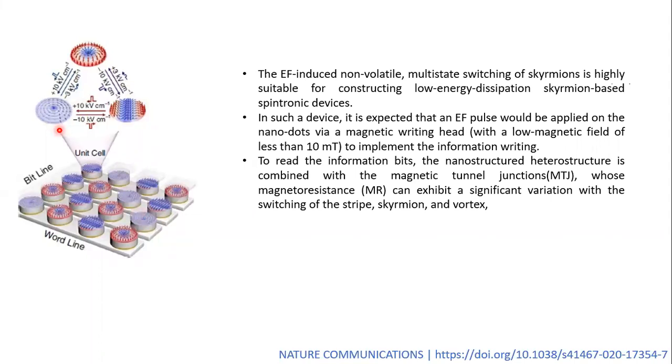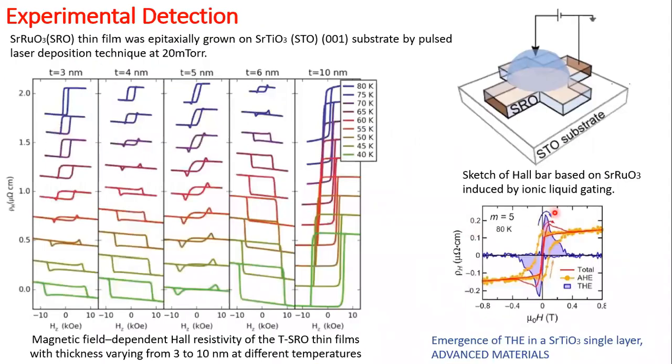One more thing, in this case we have the skyrmion with topological charge +1 and the skyrmion with topological charge -1. Now you can ask whether we can use these as 0 and 1. We cannot use them like that. First of all, to retain the skyrmionic state, we have to keep on applying the magnetic field. That destroys the non-volatile feature in this type of experiment.